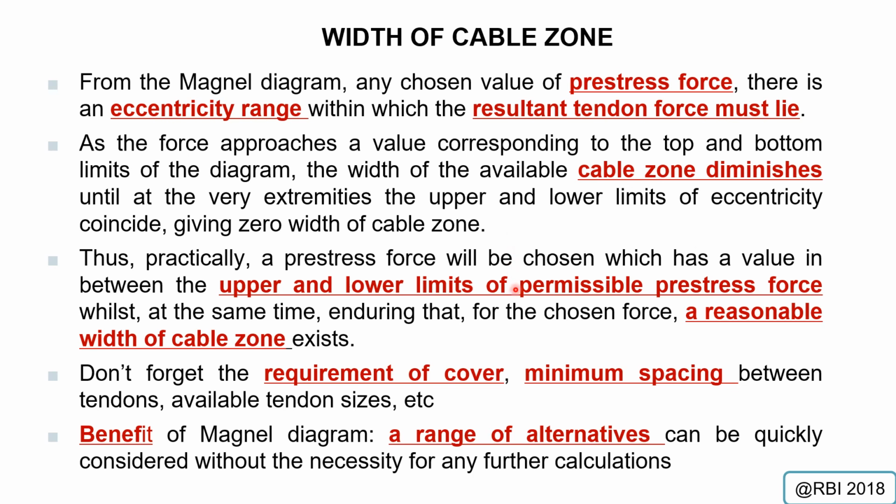So basically, a pre-stress force will be chosen which has a value in between the upper and lower limits of permissible pre-stress force, whilst at the same time ensuring that for the chosen force, a reasonable width of cable zone must exist. Okay, so don't forget the requirements of cover, minimum spacing between tendons, available tendon size, etc. They must be considered when you determine the width of the cable zone.